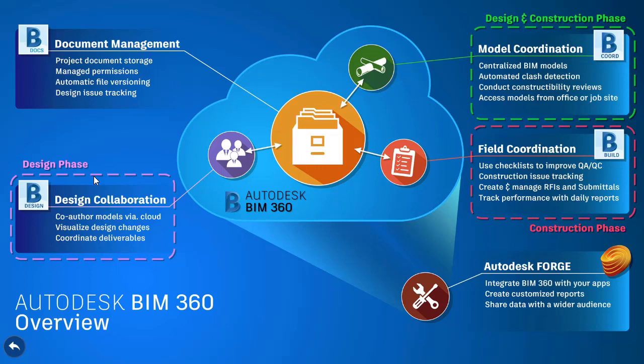It's going to let us create data shortcuts and references as we would traditionally do on a shared network drive or in a local office type of space, and it's going to allow us to do that work in the cloud. That's also the same tool that many of our friends on the architectural side have been using with their Revit to work on architectural projects in the cloud. Now that functionality has recently been extended to support Civil 3D projects as well.